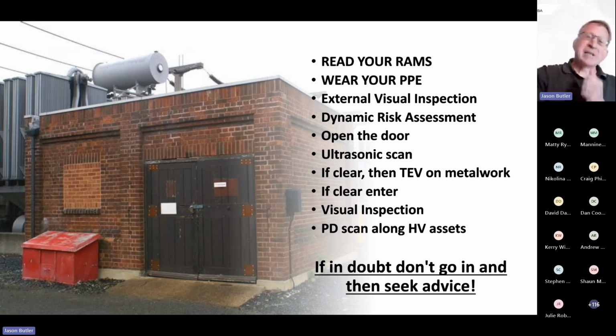Please, please, please wear your PPE, read your RAMs, and before you go in there, do a dynamic risk assessment. It's probable that no one's been in there in months. So look at it and ask, does it look safe? Is the lock in place? Has it been vandalized? Is there a forest growing out of the roof? Is it likely to be damp inside? All those things should give you the confidence to open the door.